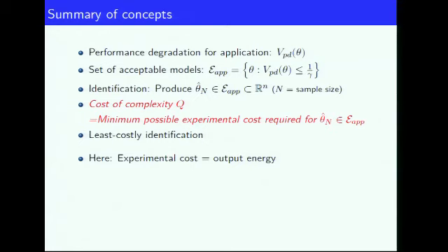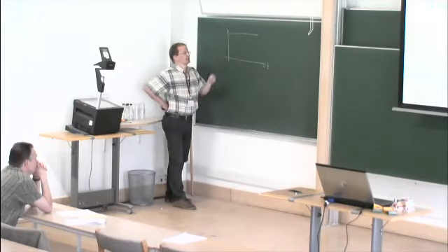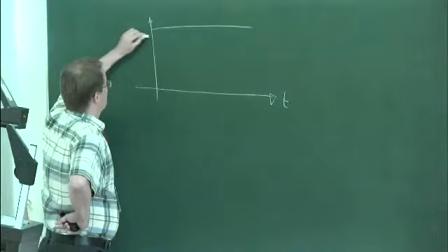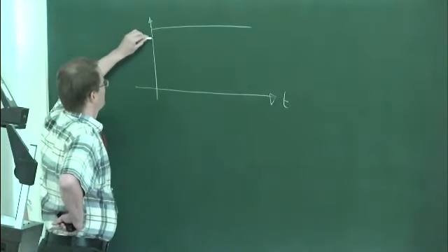And often the yield is maximized by being as close as possible to this constraint. That gives us optimum reward in terms of profits. Now, then we try to put the set point as close as possible to this bound.